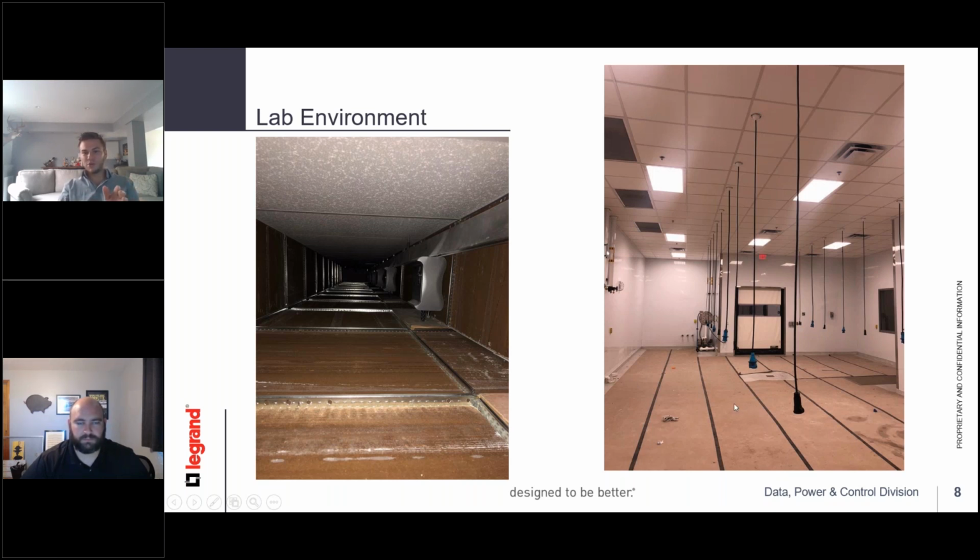We said, okay, great. What we'll do is we'll do these whips separate. And then they purchased a seal-tight grommet up here that's watertight as well. Down below, we are using Meltric connectors and then some Leviton watertight connectors as well. The benefit of those is that they can be washed down. Those are good in washdown areas. It's not going to hurt anything.